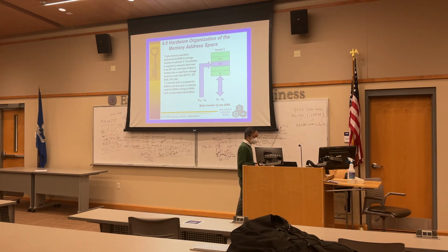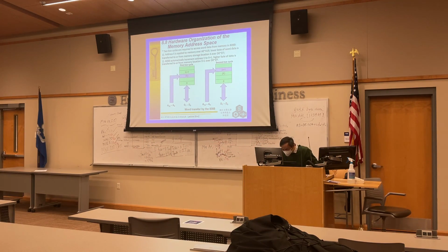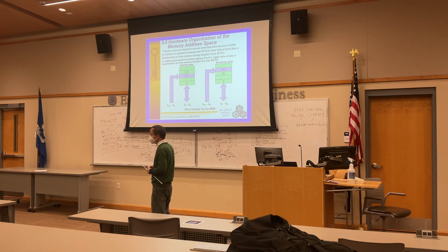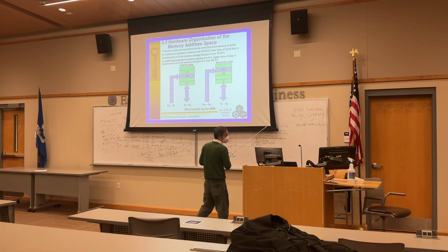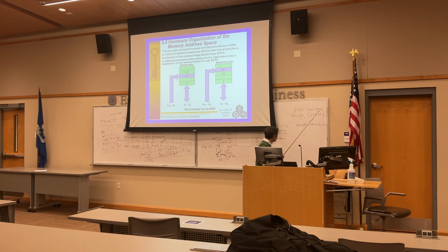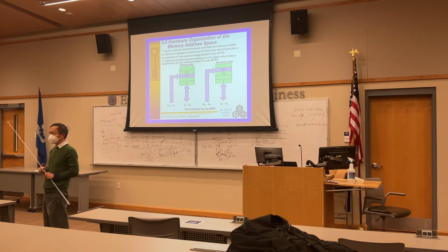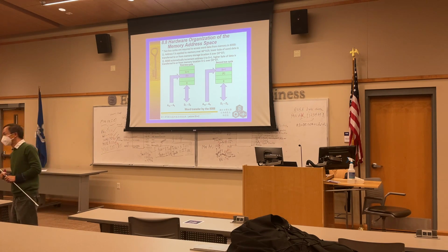However, if this is 8088 with word data, and we just change this one to AX, how many bus cycles do we need? We need 2 bus cycles, because your data bus is only 8 bits, so each time you can only handle 1 byte.